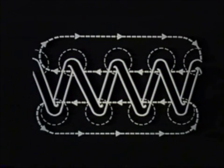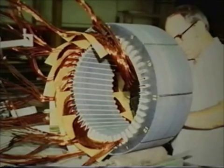You'll remember from our discussion of electromagnetic induction that if the strength of the field or flux density and the rotative speed are held constant, the magnitude of the induced voltage is directly dependent on the number of loops of wire in the armature coil or coils. Engineers often design several alternators of the same output capacity to have different output voltages by using identical fields and exciters, merely changing the number of loops in the armature winding coils.